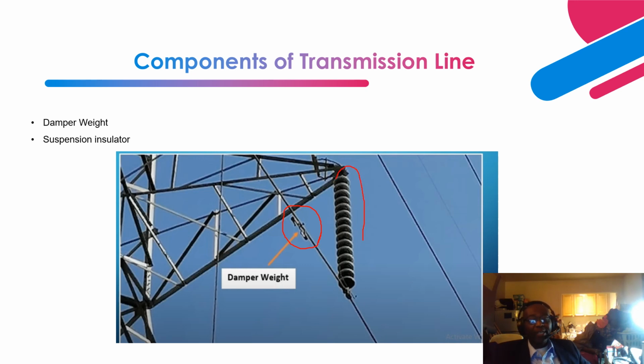Okay, so this one is a suspended vertical insulator. Basically, it provides insulation from the phase conductor to the cross arm conductor. As you know, the cross arm is a ground plane, right? So the goal is to provide the mechanical support. It's doing two things. It's providing a ground plane, and secondly, it is providing the mechanical support to these phase conductors, to keep them in place, to prevent them from galloping or clashing into other phase conductors. So that is what these components are.